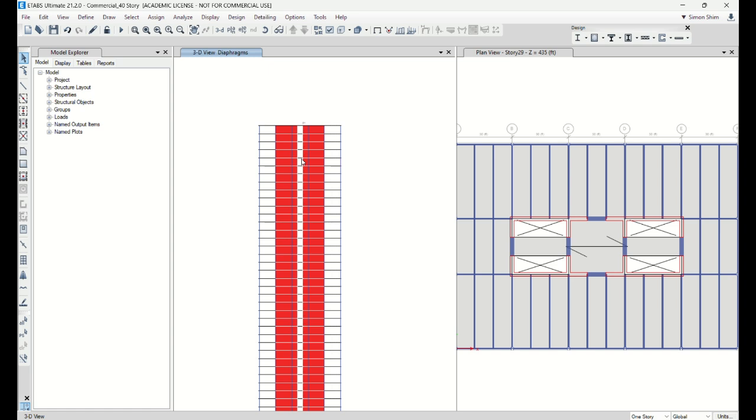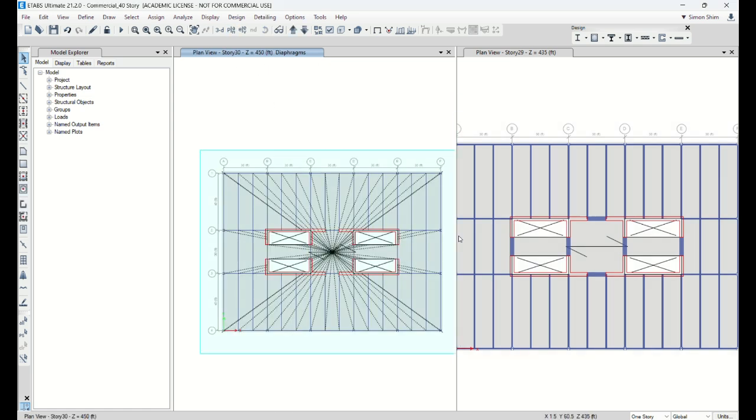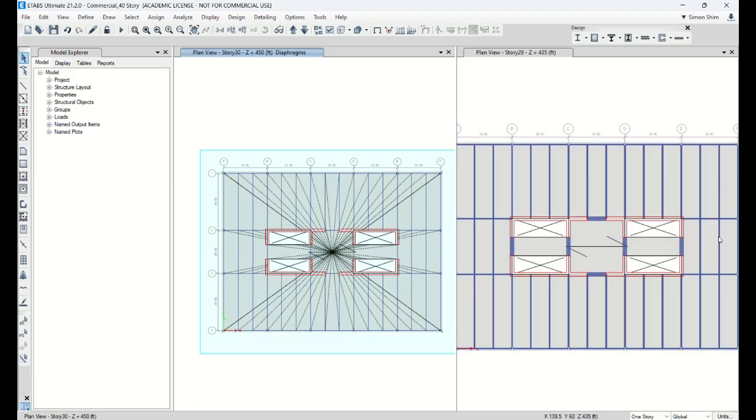They should have their own diaphragm. These diaphragms actually do their own work. I will explain later. So I assign the diaphragm. I'm gonna just put this on the plan and you see all the indications of diaphragm. All the nodes on this floor are tied by this dashed black line, and all these nodes are tied and bounded in their diaphragm. So this is the floor diaphragm.